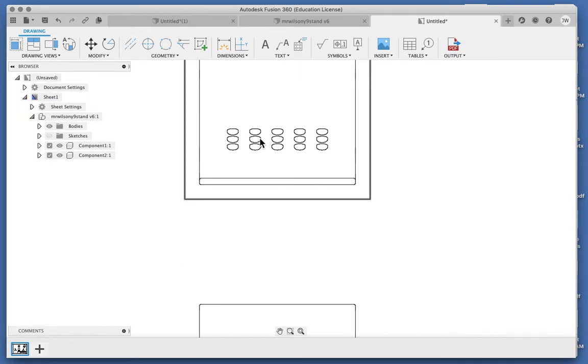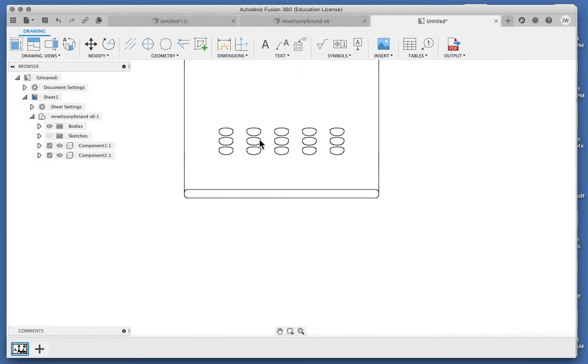So to do your dimensioning, you'll need to zoom in, and you'll press D for the dimension tool, and you'll see that as you move around, you can pick up certain points on things or certain ends. So I can come into this here, click at that point, come across to the other side, click, and then drag down, and that's going to put in the dimension for that overall width.